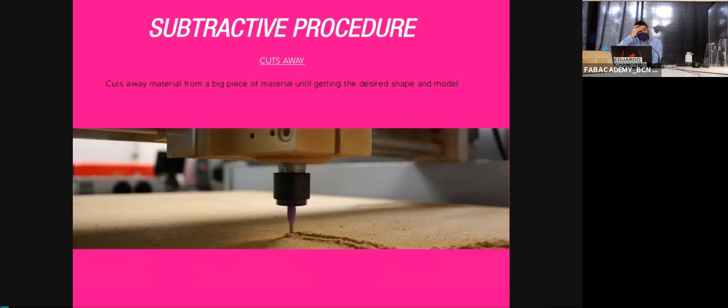It's a subtractive procedure. If we want a simplified approach, imagine a big driller attached to a machine. Basically, we are cutting with a rotating cutter knife. That is the milling bit. There are different terminologies for that, but it's a milling bit, and in this case you will use what are called end mills. They are flat or round end mills, but that's only a small part of the family of milling bits. Basically, we take our driller and start cutting the material by making small cuts at really high speed until we get the desired cut.